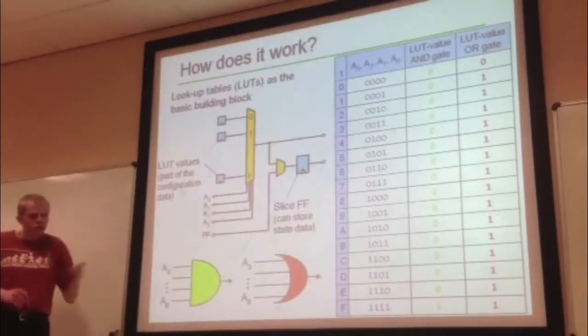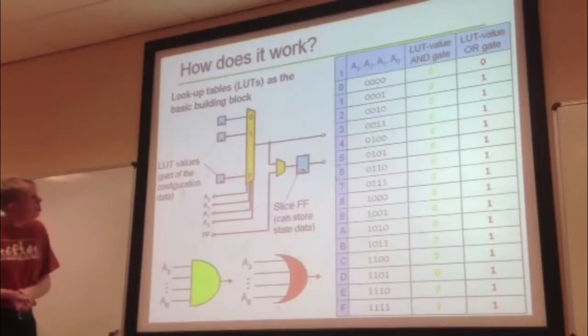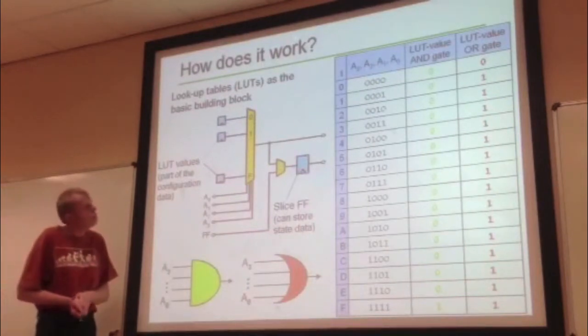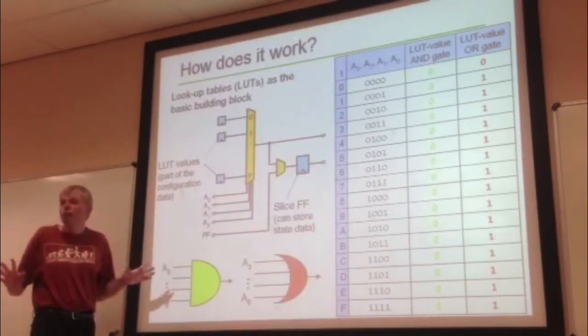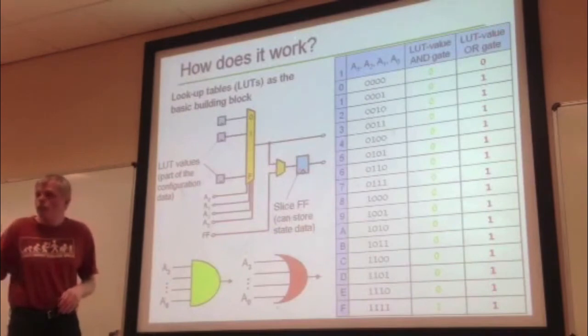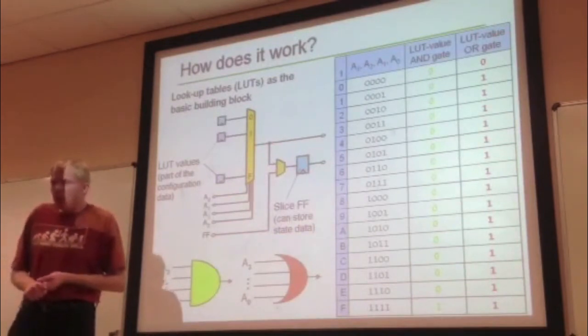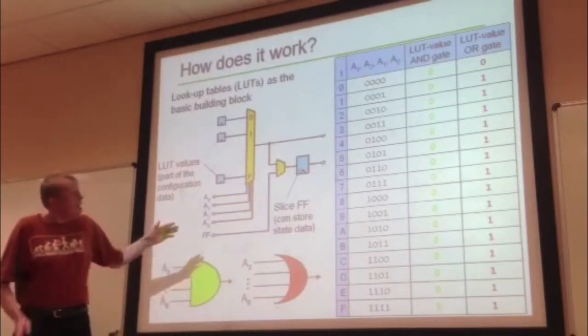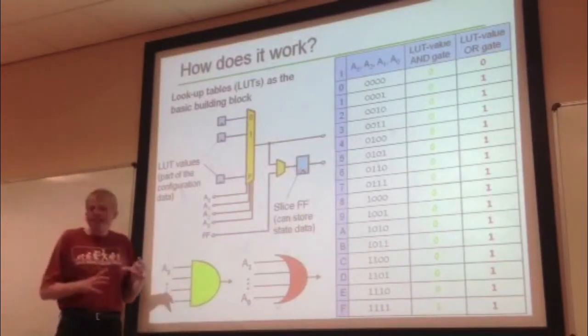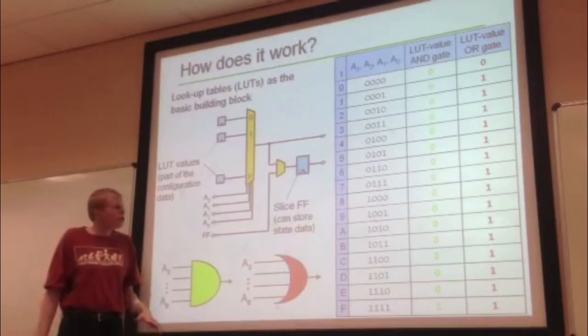Okay, very shortly, I had this slide before in this ultimate programming, but just to make it complete, how you implement logic. The basic building block to implement logic is a lookup table. The thing works very simply, like what you learned in the first semester, how an AND gate or an OR gate works. You simply look in the truth table: if two inputs, for example for an AND gate, are 1, then the output is 1, and in all other cases it's 0. And you implement logic on the FPGA inside the logic cells using exactly the same idea.